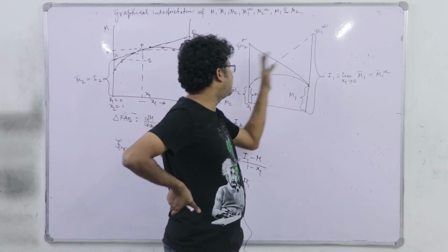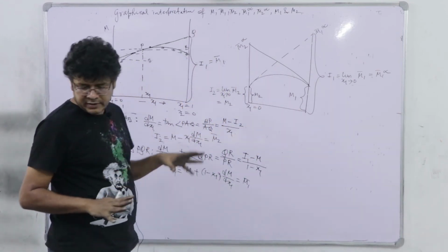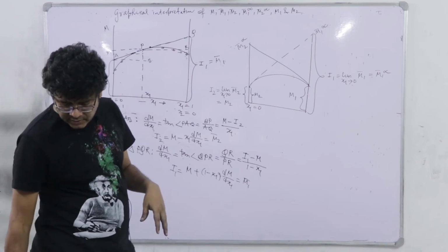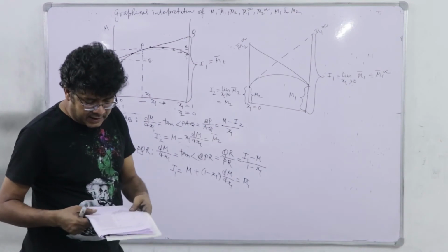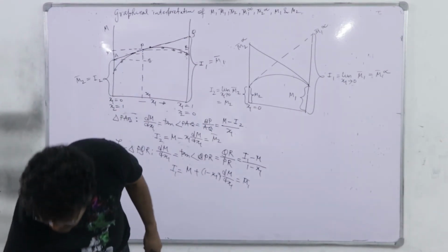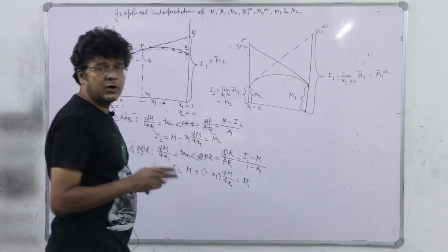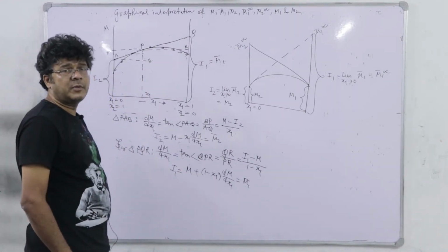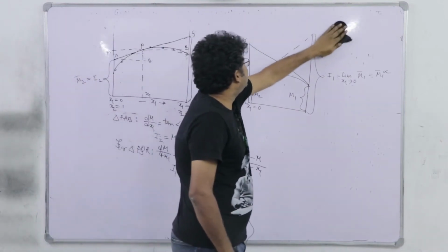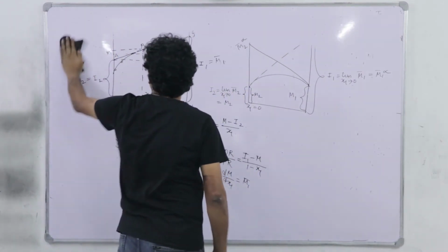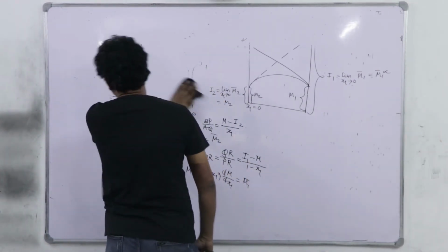Okay. So, from there we can graphically calculate, there is the graphical interpretation, and from there even if this equation is not given, we can graphically calculate the partial molar properties at a specific concentration. We can also solve for pure species property and infinite dilution property. So, with that understanding of this partial molar property for the binary system, let us move on to the calculation